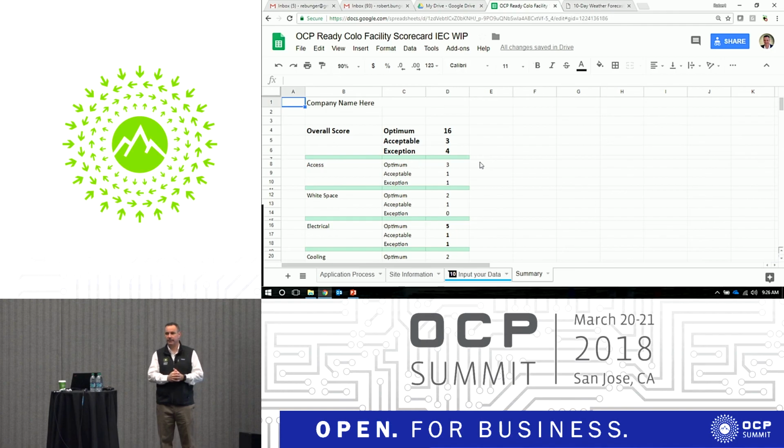Thank you. Last question. Is this across Project Olympus? Yes, CG19 definitely. They're all very similar specifications? Yeah, I think so. There's some minor differences in terms of the ITIC curve, the 20 millisecond ride-through times. There's some sag conditions down to 140, 160 volts, things like this. I know there were output specs from the rectifier to the bus bar. There's definitely specs there for the minimum requirement for AC into the rectifiers. We've got to look at that.